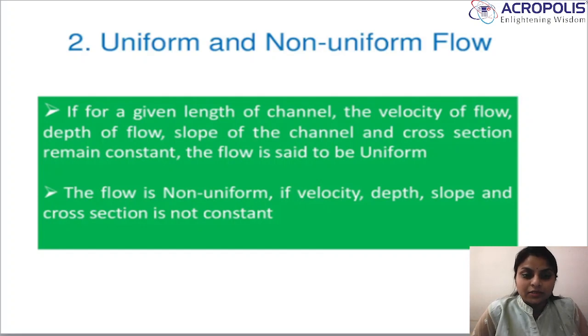So in the river or in the case of a canal, you have to take the mean velocity and the mean depth. One single velocity will not actually explain anything mathematically. In case of uniform flow, what happens? The fluid characteristics at all those points, A1, A2, A3, B1, B2, have the same velocity, which means the mean will be the same. It is an ideal condition. Again, steady flow is also an ideal condition. It will exist only rarely, and can be achieved in a laboratory.